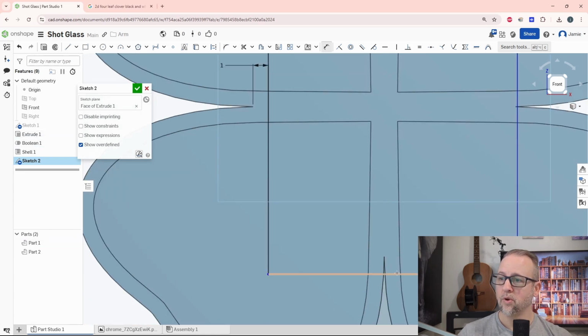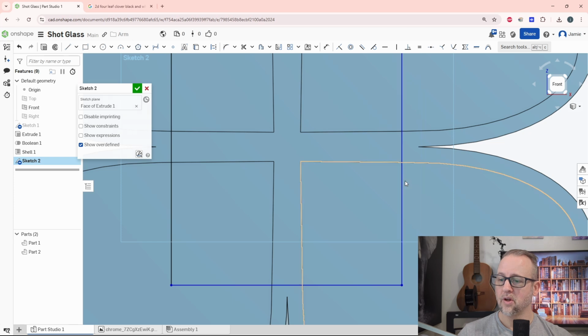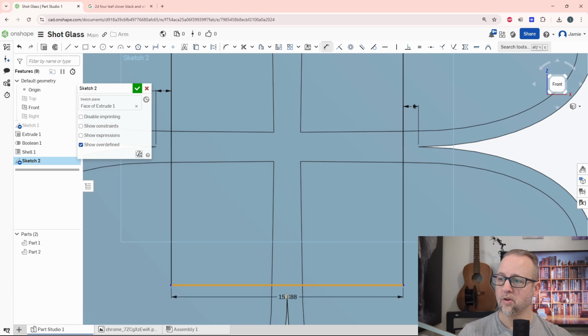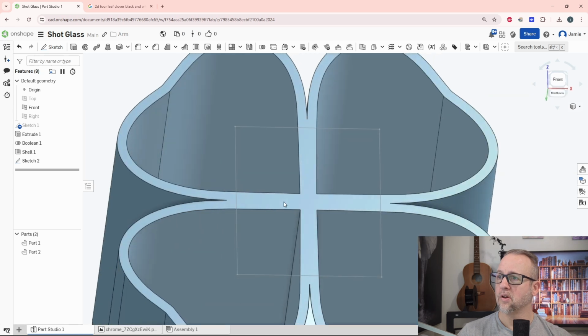Okay, 1 millimeter. I'm going to grab this, and I'm going to hit escape, space bar, get out of that, pull that guy down, and pull this guy down. Now we're going to go D for dimension, 1 millimeter. Then we're going to do 1 here. Okay, there we go. And now we can take out that material. Now we can subtract that.